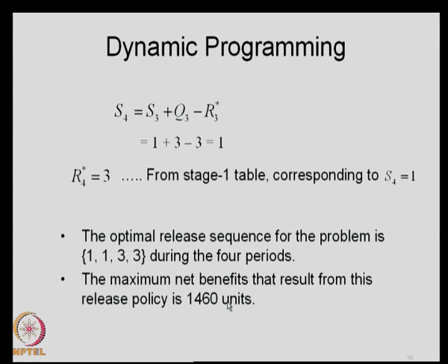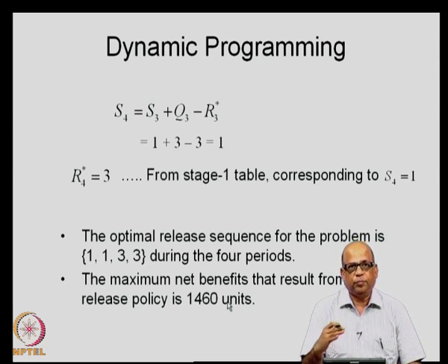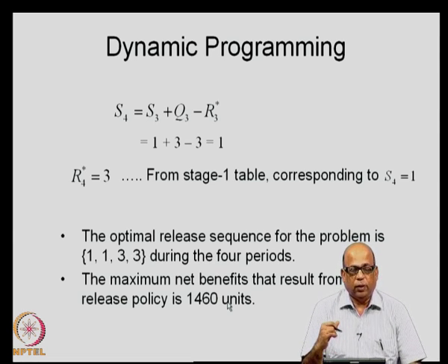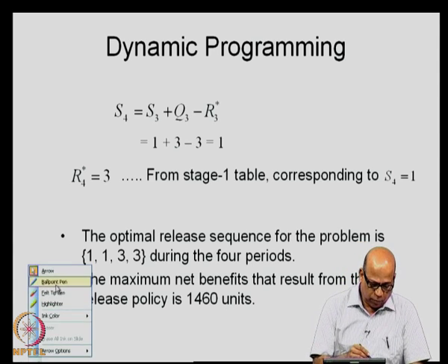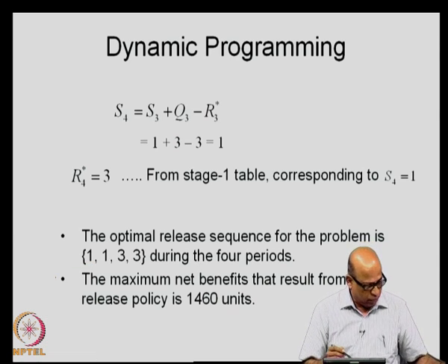So, this is a classical reservoir operation problem when you have discrete states of storage, and inflows are also taking on discrete values, and release therefore, will also take on discrete values, and we have ignored the losses here. Now, this is a typical problem where we have specified the storage at the beginning of the time period. Let us say